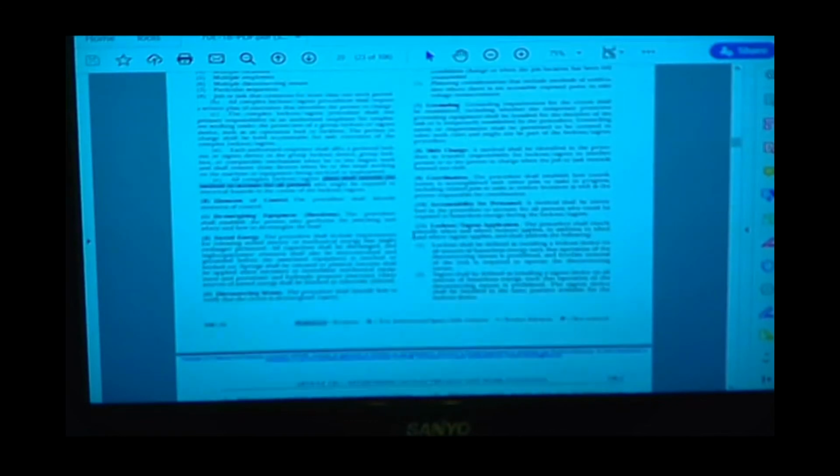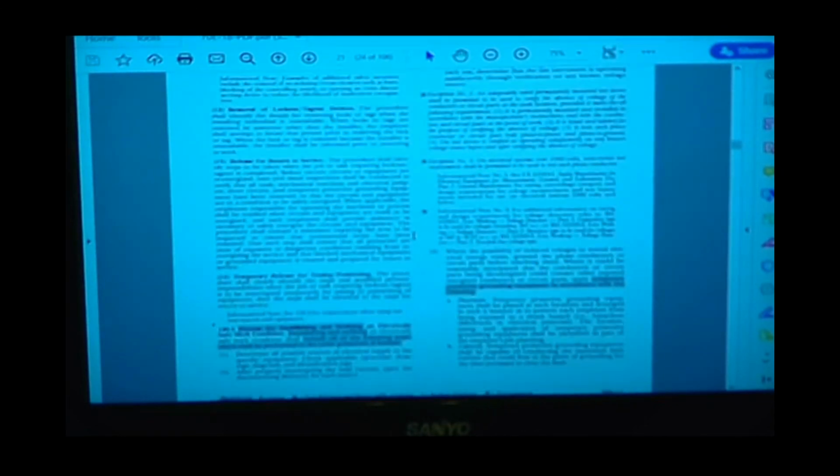Simple procedure is what you do normally. You're going to shut off the equipment, you grab the handle, pull it down, turn it off, you put your lock, your tag onto it. When you're done with your work, you take your lock, your tag off. It's that simple. The complex procedure is different. You have multiple crafts, multiple equipment, multiple energy sources. It doesn't matter what it is. But there's one person physically in charge of locking and tagging everything. So this gets real complex, and there's lots of variations of each.